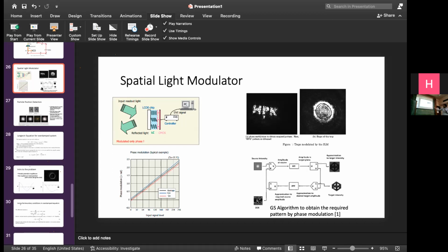If these are in a straight shape, then light goes very little through this material, and if these are perfectly aligned, then the path of the light through it will increase, and effectively I create a grid of 500 by 500 pixels. This is what that device, the spatial light modulator, does, and it will tune my flat wavefront into whatever shape I want. A wavefront is something that has a constant phase, right? So I can tune my phase through this kind of device.